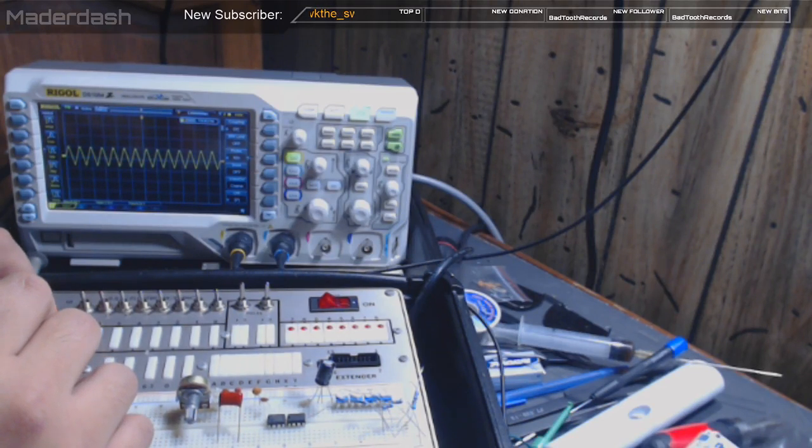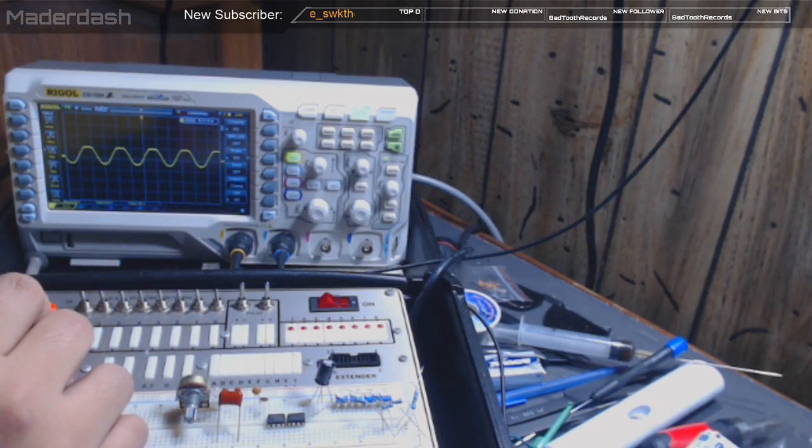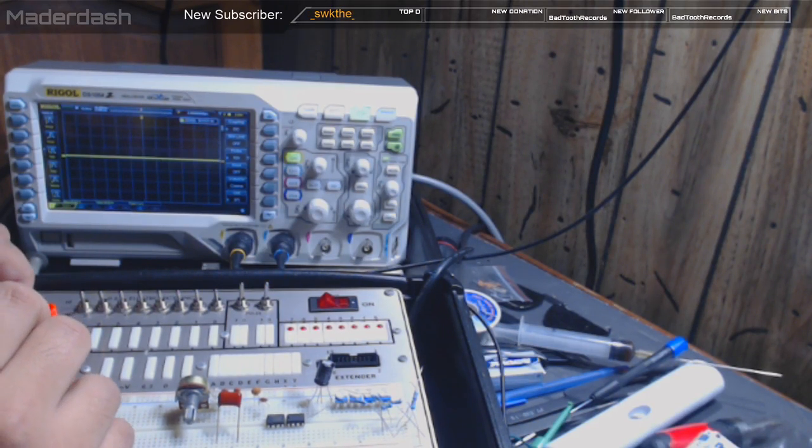The sine wave needs a little bit of help. It clips a little bit, see? It looks like some transistors are weak or something on it. Now the square wave doesn't look bad.